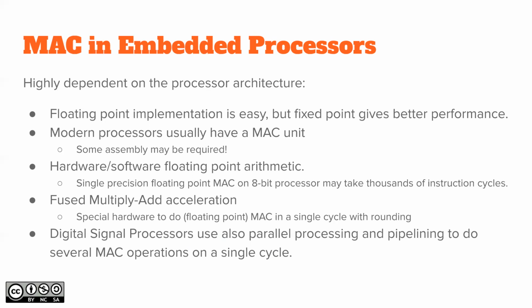Thinking of a system that makes a lot of those MAC operations, it might mean that you cannot put that processor core to sleep at all since it's doing these floating point operations. So in that sense, you need to think of whether it is smarter to make a fixed point system.